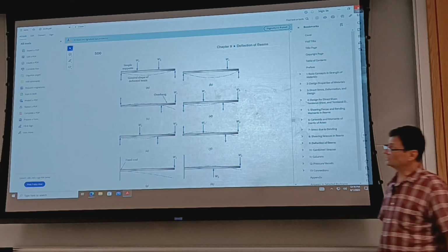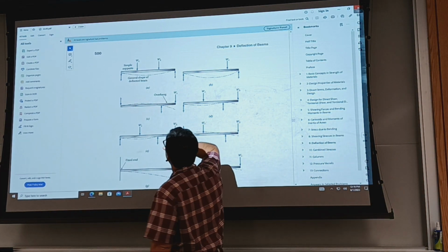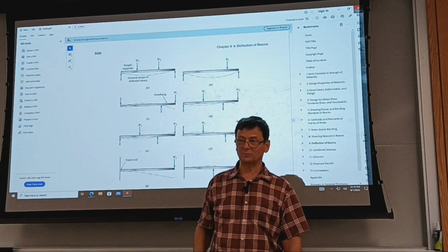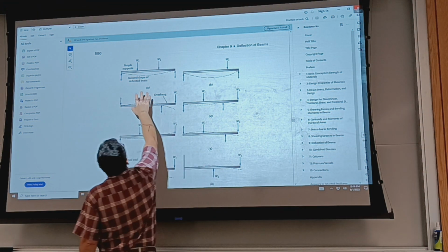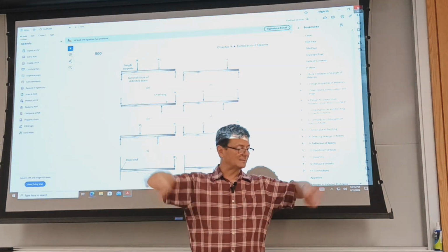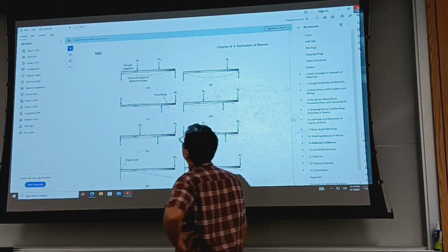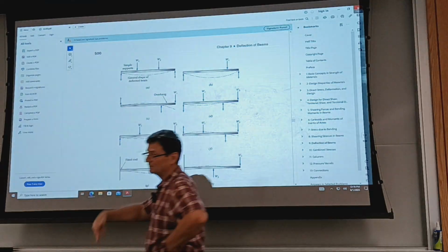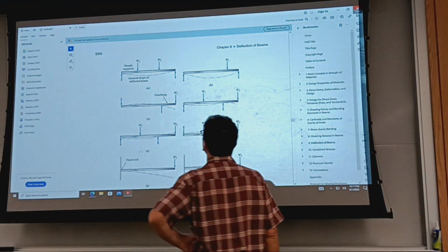It shows here a simply supported beam with two supports at the very ends, right? And it's loaded with two loads in the middle, and it shows the shape of the deflected beam. I think we even looked at this. So a smiling beam, it deflects and it smiles. We're expecting a positive moment. And by the way, the deflection is considered positive with the y-axis down.